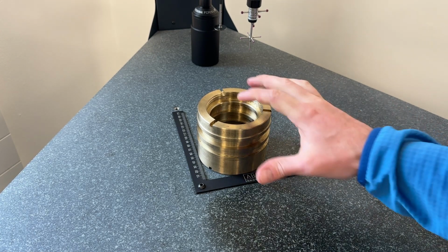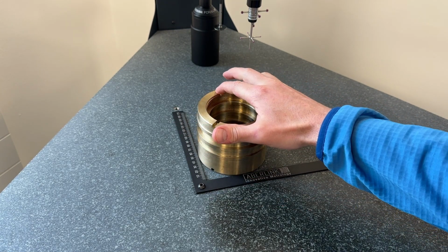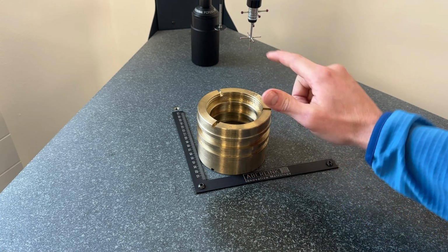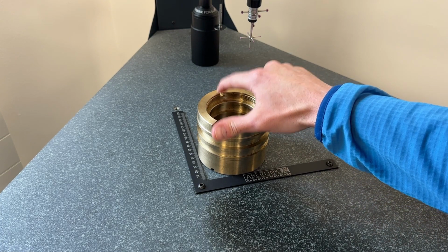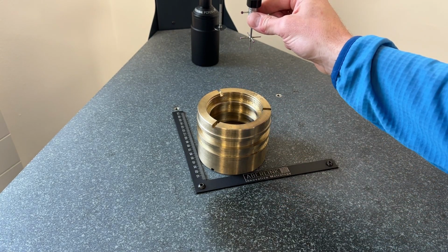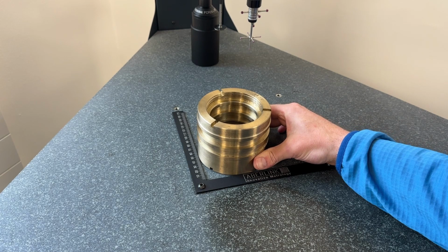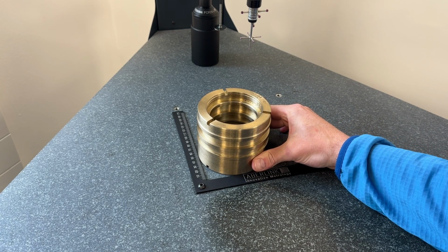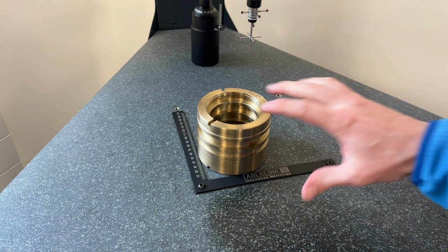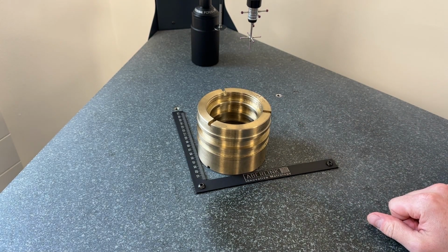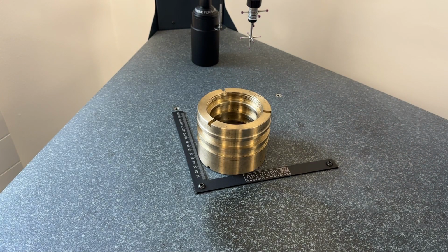So in this system I've got the plane, the outside diameter circle, and then a midline from the slot. The idea is we're going to utilize some probe moves and a pause to drive to where the CMM thinks this slot is. You can imagine the probe will drive down to a certain position, and then the pause will allow us to visually rotate the part on the Z axis until it visually lines up with the stylus. We then press enter, and because we've got it visually close enough to the reference system previously, it will find the reference features fine, clock itself in, and run the entire program.